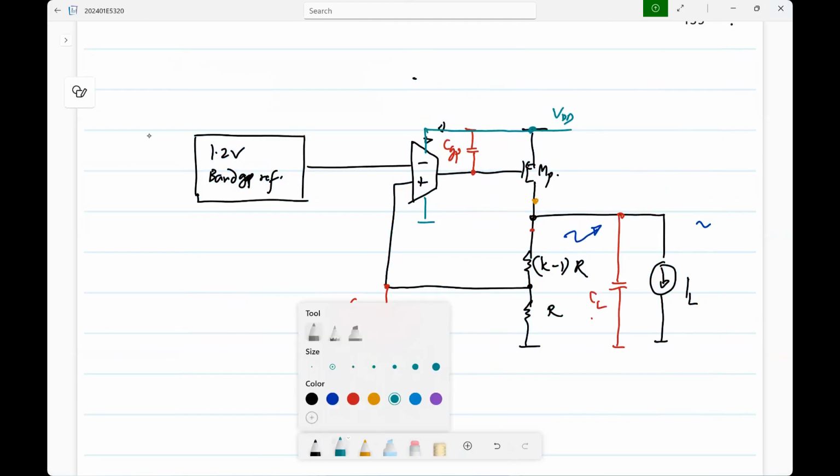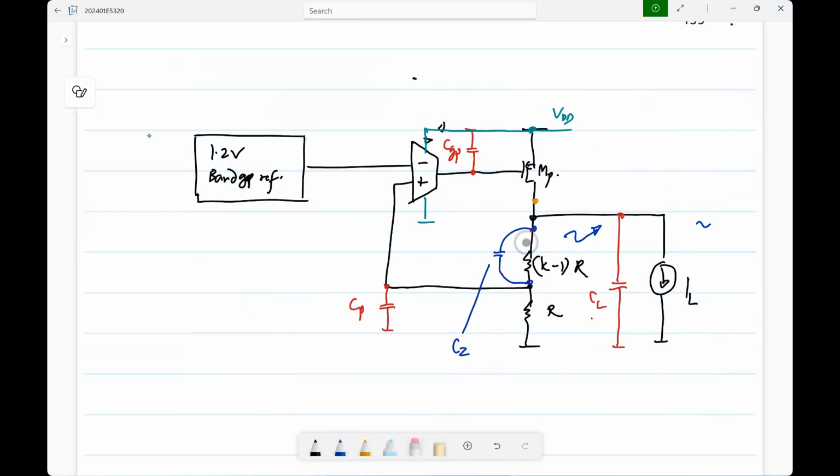Now one thing, of course, you will always do is connect a capacitor across this. Where do we add this? What does this do? The phase shift from there to there will be reduced. You have to make sure that this 0 is below the unity loop gain frequency so that basically at the unity loop gain frequency you have the capacitive divider, not the RC filter. Okay. So if I call this A, B, C,